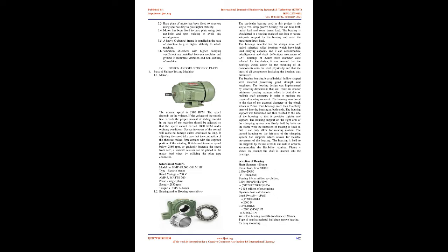Methodology. Preparation of manufacturing layout using CAD software. Selection of C-channel and vibration absorber for foundation. Selection of bearing, chuck, weight hanger etc. considering loading and operating conditions. Drawing of parts and assembly in CAD software. Analysis of various parts using FEA software. Manufacturing of parts. Assembling of all parts.